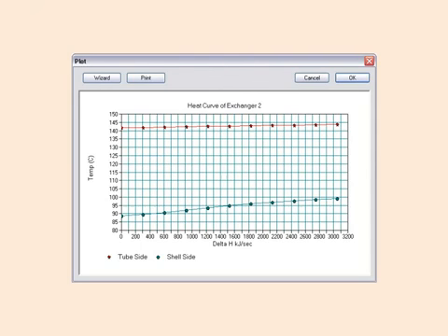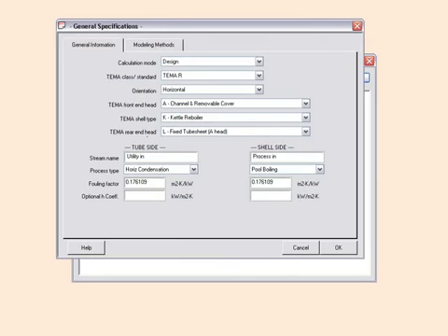And the first thing we'll see is our temperature enthalpy diagram. The tube side, which is our steam, is a relatively constant temperature from 143 degrees Celsius down to about 142. And our process side in the reboiler shell, it ranges from a temperature of about 87 degrees C up to approximately 99 degrees C. Now we're ready to get into the design of the kettle reboiler.